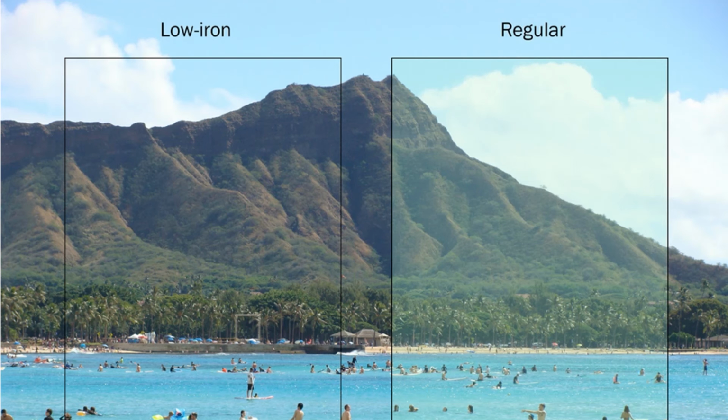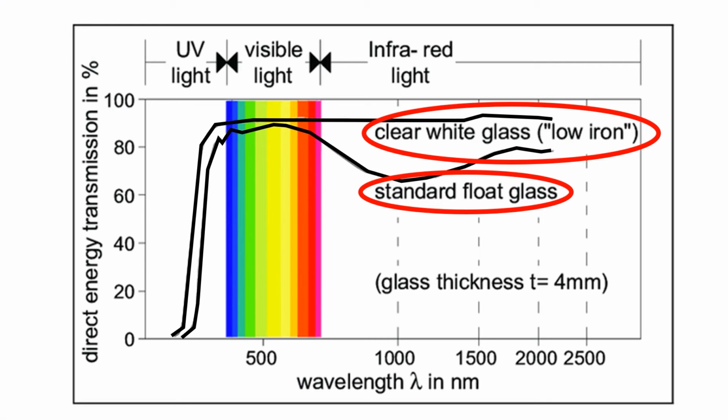Plus, there is a factor that makes the greenhouse effect worse. To reinforce the transparency of the building, extra white glass which contains low iron was used instead of regular glass. Low iron glass provides better transparency but provides more energy transmission too. Due to this property of low iron glass, the greenhouse effect is getting worse compared to using normal glass.